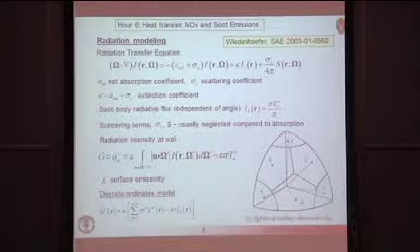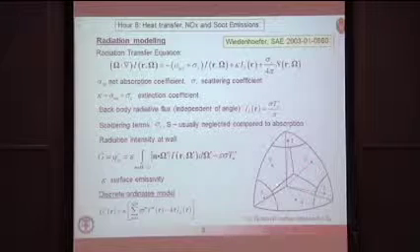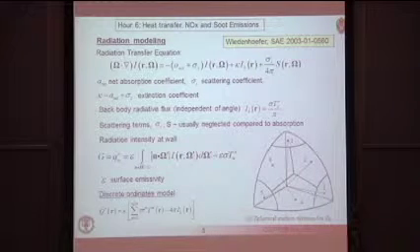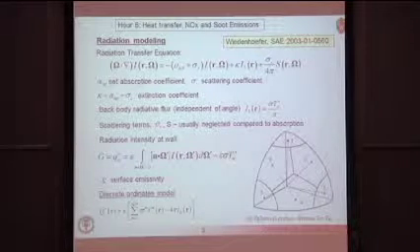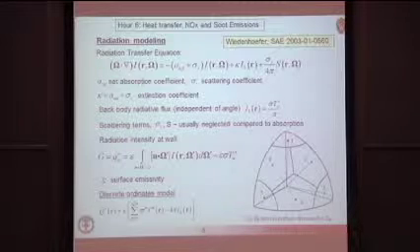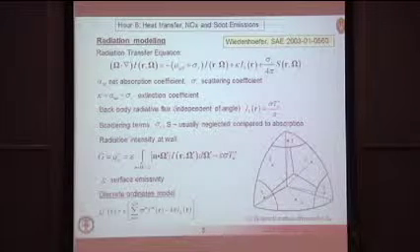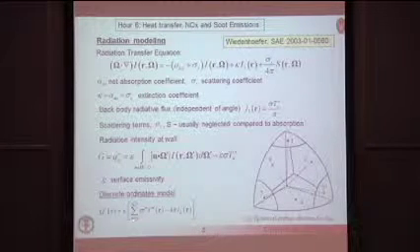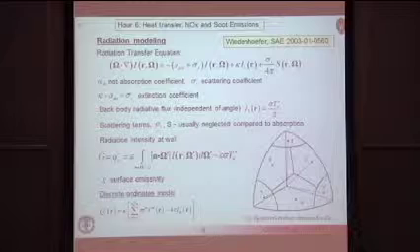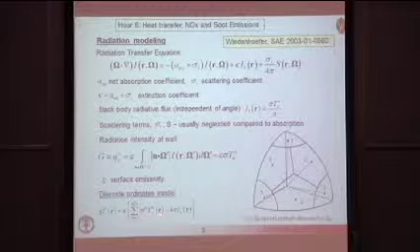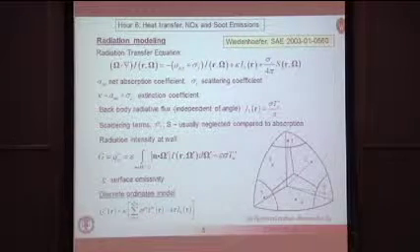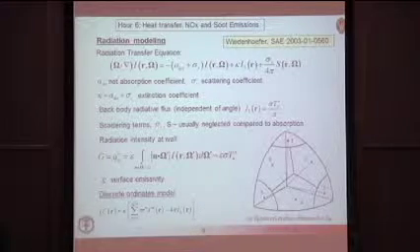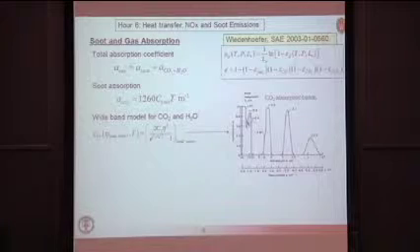And so here you see those preferred directions for a case where we had 6 ordinates. So in each cell, basically, you have to store the contributions to the radiation flux that comes from those 6 coordinate directions. And that's what's defined here. M goes from 1 to the number of coordinate directions, the solid angle, and the radiative flux from cell to cell. So that's basically the method that's used to calculate the radiation source terms in the energy equation.